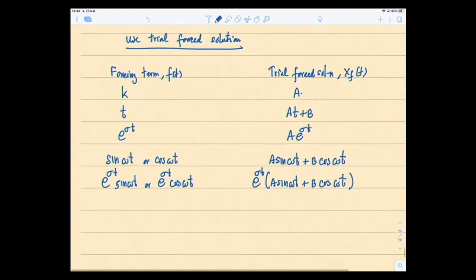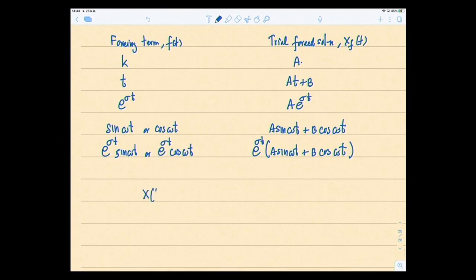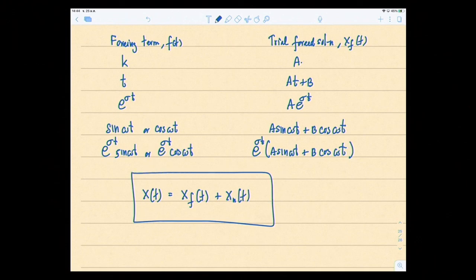At the end, we analyze both the forced response and the natural response, add them together, and get the final answer. The coefficients a and b come from the natural response, and you have to use initial values, so you have to know how to find the initial values. So I think that's the review for the second order circuit.